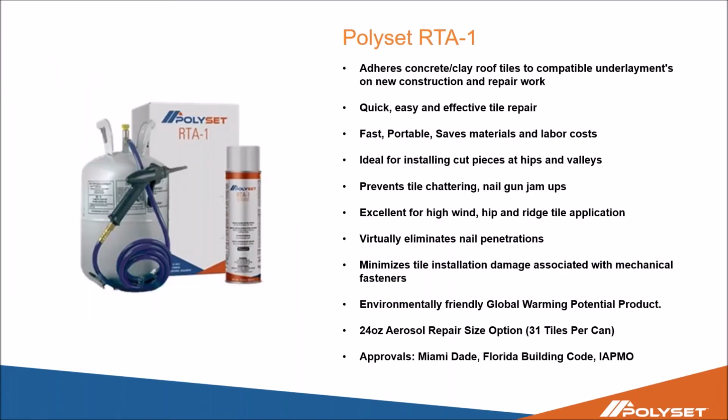So first we'll talk about the single component products. They usually come in what the industry refers to as 23-pound kits. They kind of look like barbecue tanks. They come with a 7-8 foot gun hose assembly, two mixing nozzles, and a wrench to tighten the hose to the stem valve of that cylinder. They also come in repair can sizes as well, which yield about 25 to 30 pieces of tile per repair can. The good thing about these single component products is they're very quick, they're very portable.